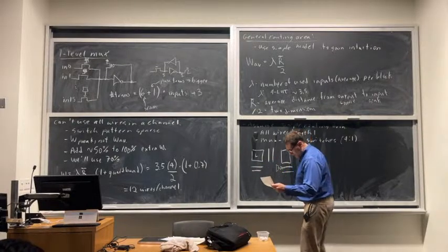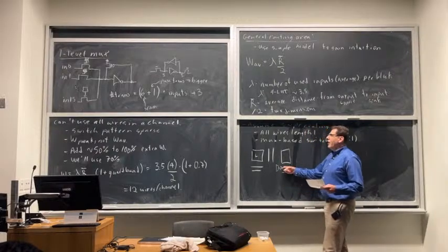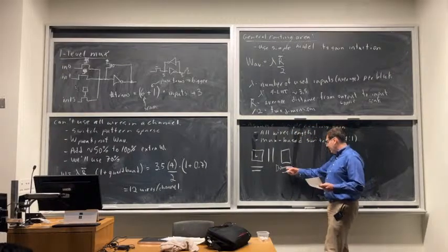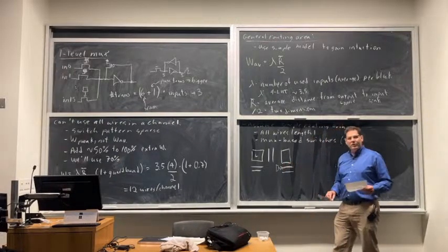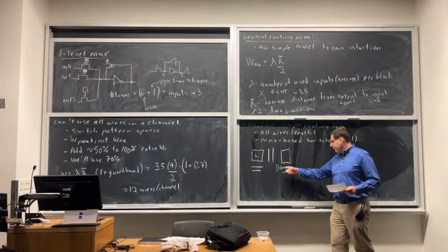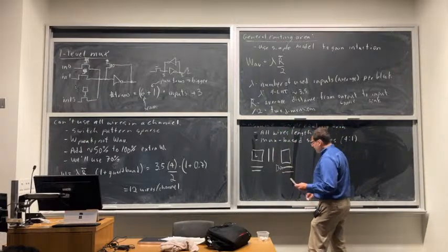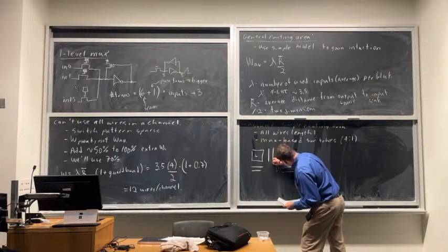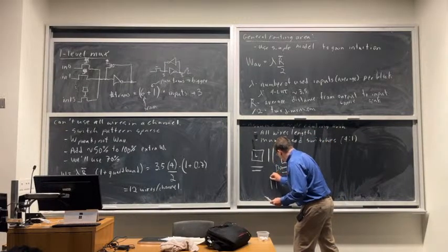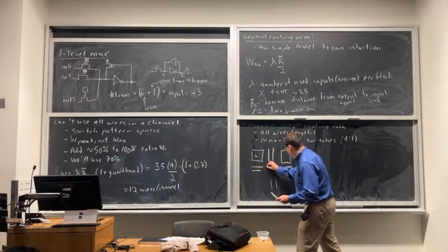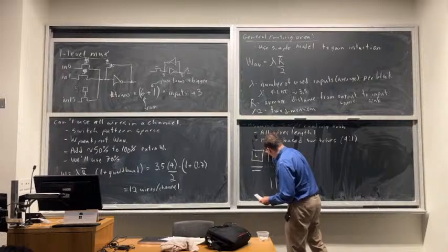And it's going to have an inverter on the output because that's what we've been putting there to isolate the capacitance. This routing wire, even though it only spans 1 logic block, is still a fair amount of capacitance. So that inverter is our friend to isolate that. With 4 inputs, we can take basically 1 signal from above, 1 wire from below, 1 wire from the left, and we can take an output. Let's say we've got an output here. And that's enough. So we have connectivity from a logic block to our routing.